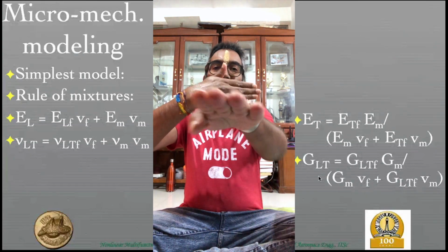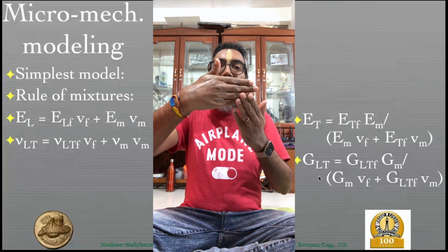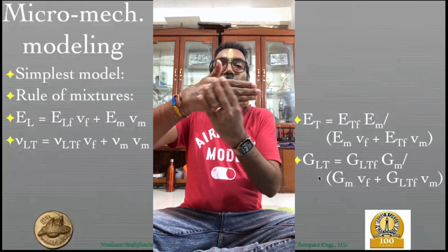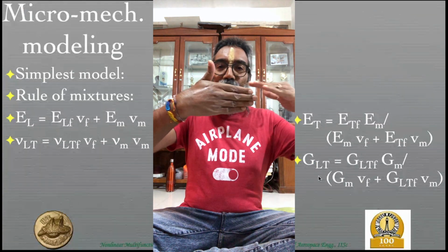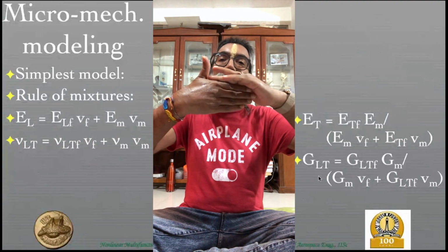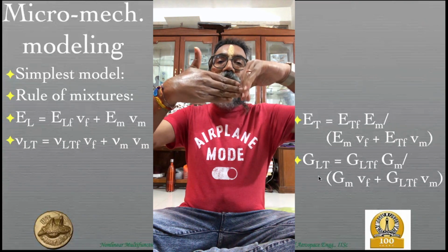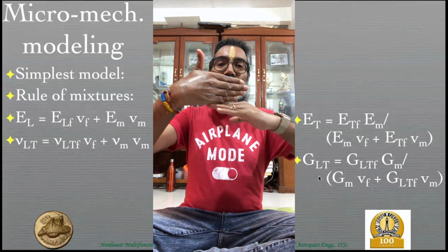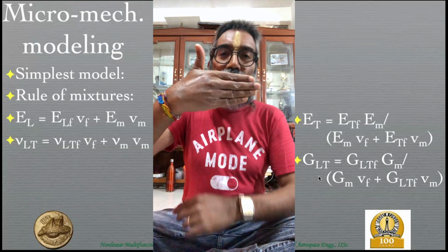So just think that the fibers are going between you and me. Now I'm only concentrating on this plane through which the fibers are coming out like this, and then on this plane I want to apply a shear stress. So that will be a tau T T prime, okay, and so that will have a complementary shear stress, which is now tau T prime T, and similarly again on this surface and this surface you would have all these stresses.